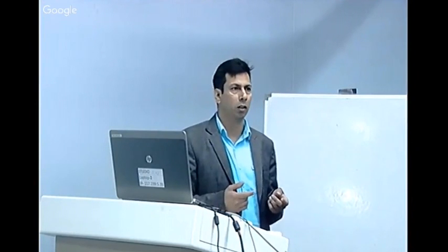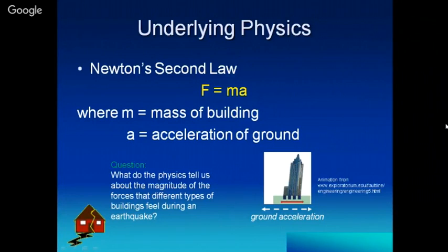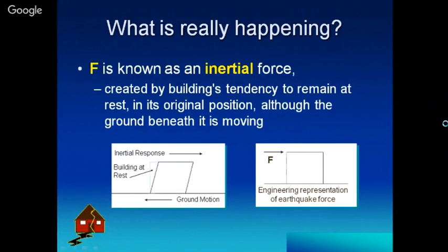In an earthquake there is a deformation of the ground, and due to that an inertia force is developed from the structure's mass, multiplied with the acceleration of the ground motion, and that gives the earthquake force. This is what we depict here as the lateral load for the buildings.